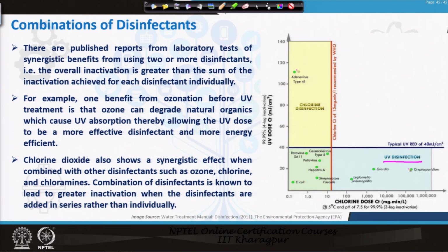This is the deactivation through UV disinfection for the different species. Now, this particular species requires a huge amount of UV dose. So, if you want to remove this and this together, you need to actually cover the whole spectrum with the UV.